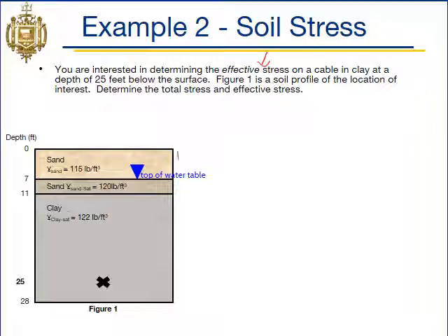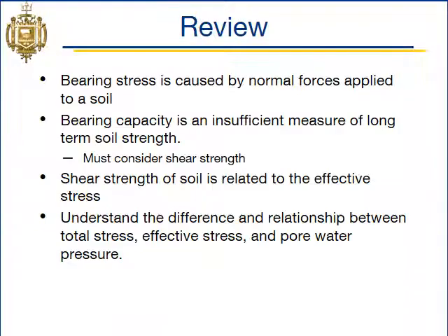You can see that we have 3 layers, right? So you'll have to do a summation of the total stress for all three of those layers. And remember that seawater is the depth of water to above our point. All right, and here's a review.